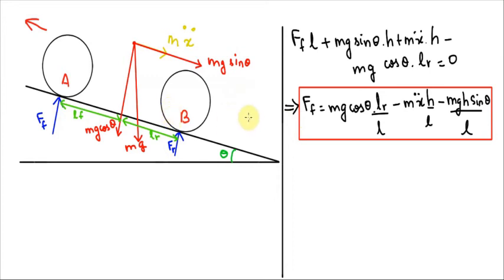Let us say that you are climbing down the slope. This will be reversed. There will be the plus sign instead of the minus sign, and whatever statements we had till now will be just reversed. The wheelie will be quite tough to do because the value of Ff will be just too high and will go on increasing. So considering the dynamics of the bike, considering the forces that are acting on the bike, we have just proved that a wheelie is so much easier to do with the increasing angle of the slope.